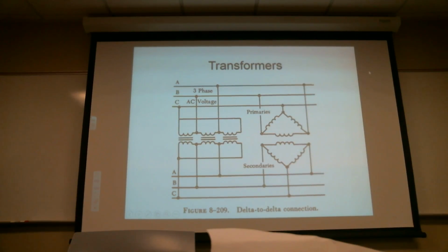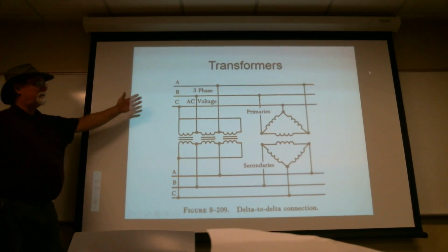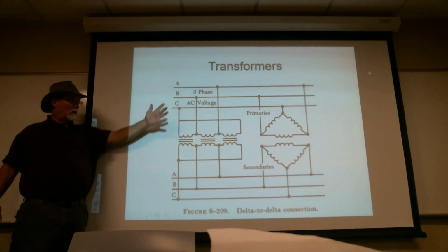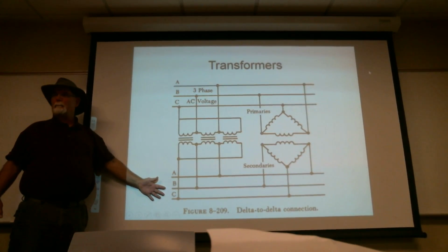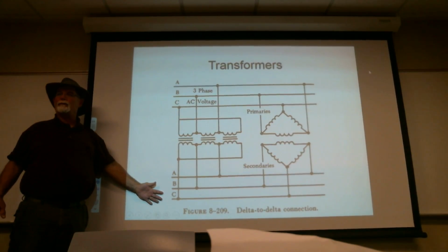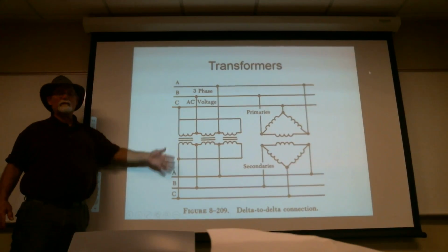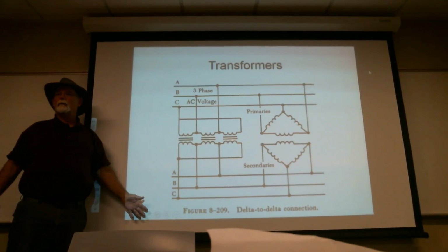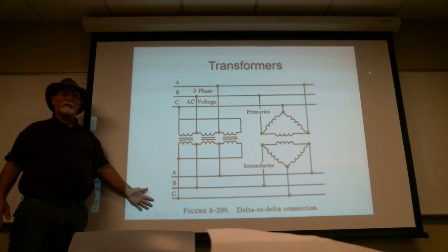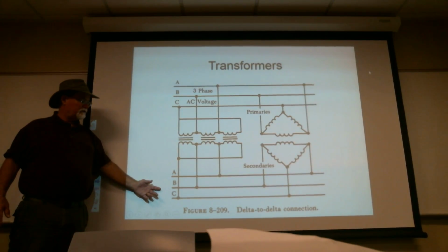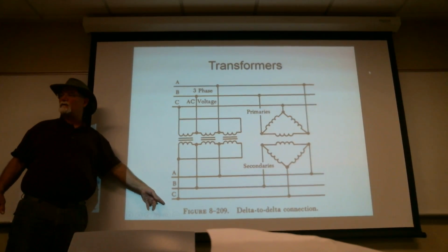Now the upside of this is all of these are going to be phase shifted, but they're going to be phase shifted the same amount. So as long as I don't intermix these two somewhere down the road, which you normally wouldn't because of different voltages and different currents, the relationship between A, B, and C remains the same.